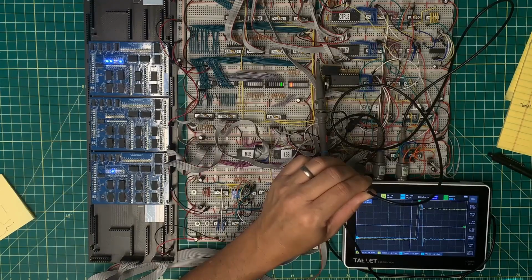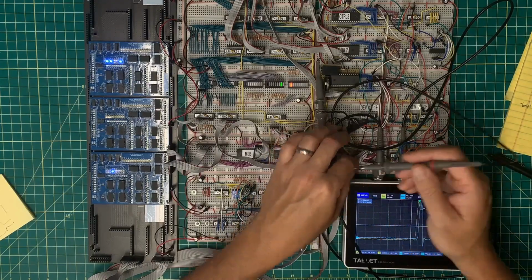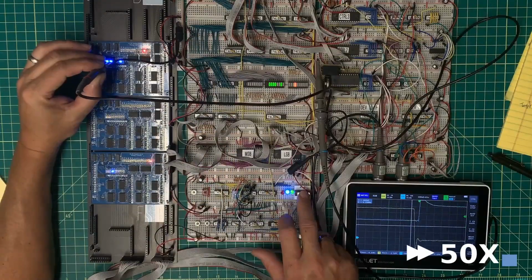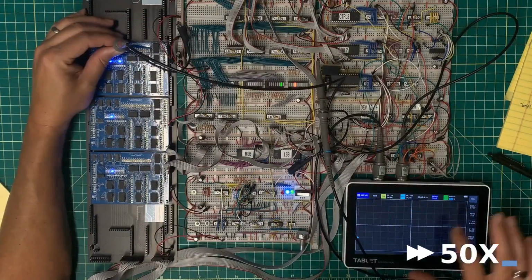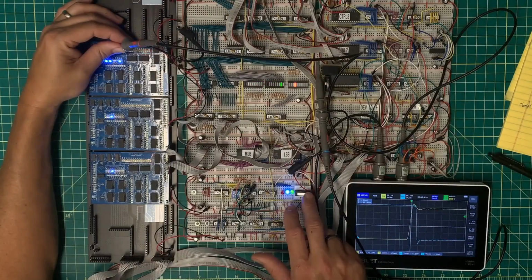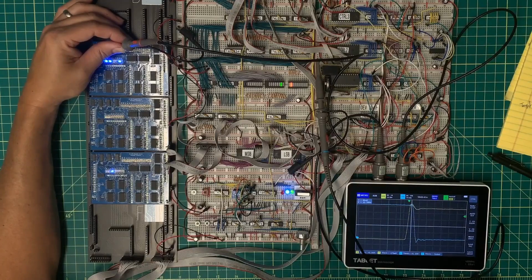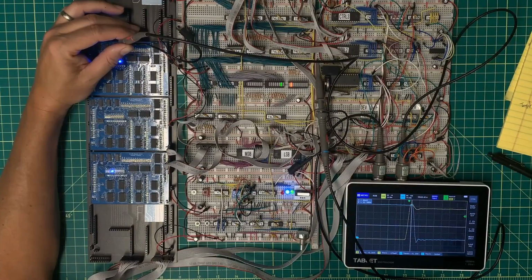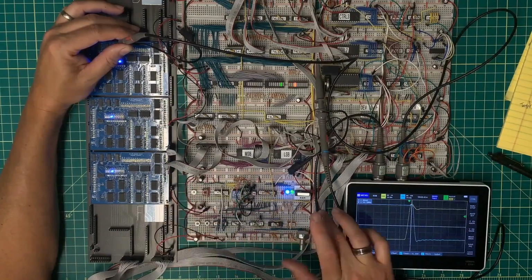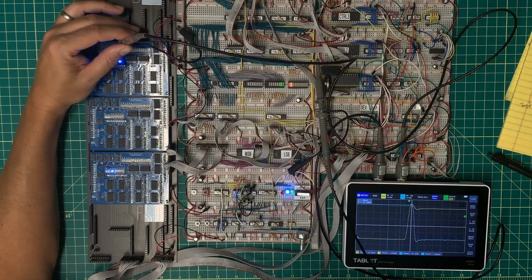Well, that was correct. That's the correct signal going out. Compared to the clock after reset, it's going down. That is not the right signal. That should be a rising pulse, not a falling pulse here in the blue. I need to think this through a moment, but I believe that is ultimately what is my problem.